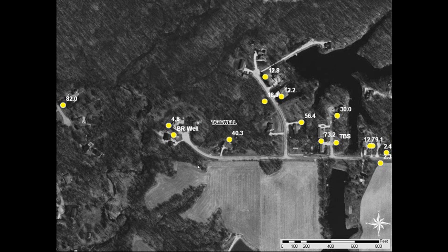I show this just because one of the issues is variability. This is Tazewell County, Illinois, which is a project that Tom Holm from the Water Survey and I completed about 10 years ago. These are arsenic values at a series of homes. The total distance here is less than half a mile, and it varies from 2.4 ppb, which is below the standard, which is 10, to as much as 82 parts per billion, which is 8 times the standard basically. And over very short distances, a couple hundred feet or less, you can have an order of magnitude difference in arsenic value. And that's just a characteristic of this particular aquifer.